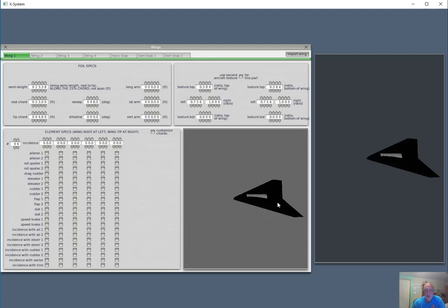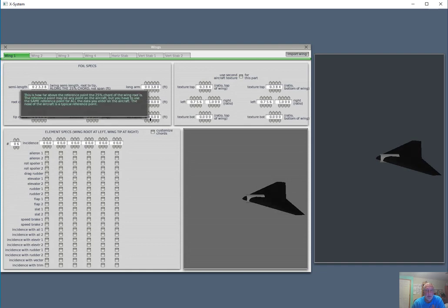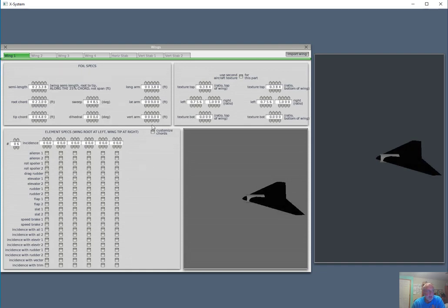So that looks like a wing of our F4 there. We need to move it to its correct position on the fuselage from the datum, so the value for the longitudinal arm is 4.8. Lateral arm is 0 and 0 because we're running the datum right through that.